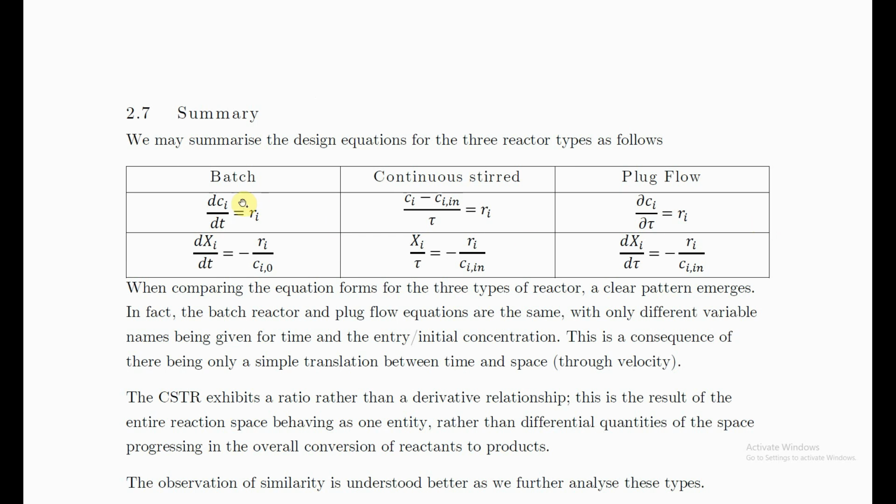First off, we are summarizing all our reactors here. The batch reactor, we said, had this mass balance, the CSTR had this balance, and the PFR had this one. And if you look across these, you can see close similarities. Here, you've got a rate of change in time equals Ri. Here, it's a rate with respect to space-time, a slightly different definition of time. I usually call this real time, and this is space-time.